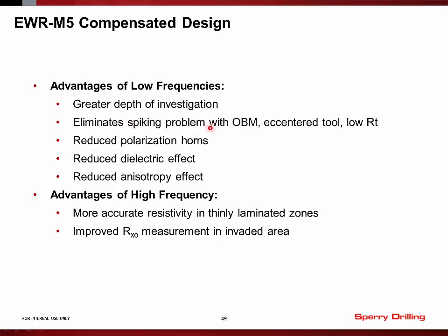There's also a problem which exists with the high frequency data when we're in oil-based mud, which is very resistive, and we're in a low resistivity formation. That produces a very high contrast in resistivity between the borehole and the formation, and that then makes the measurement very sensitive to tool position. So if the tool is eccentered or off-center in the borehole, that can cause spiking on the log, which I'll show you an example of in just a moment.